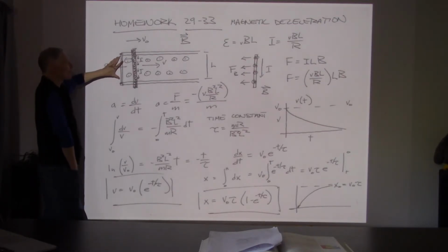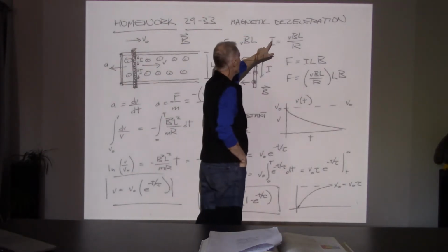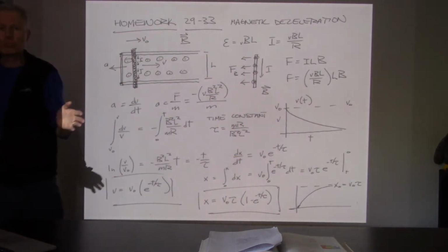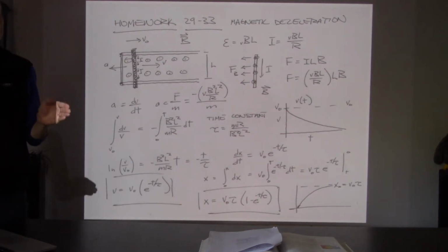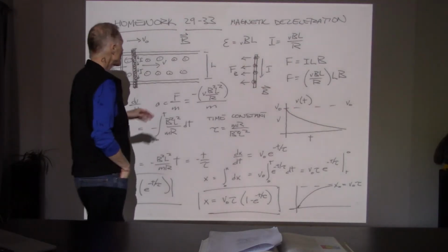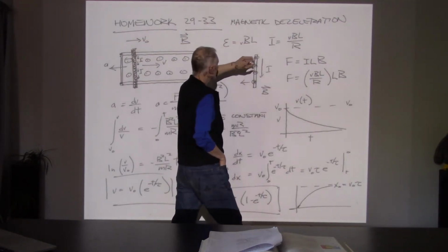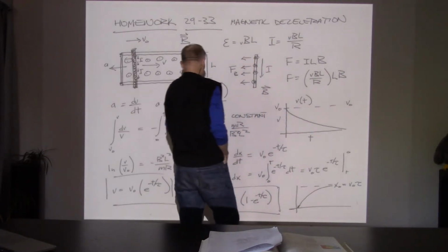Now, what happens once the circuit connects? Well, then we can start driving current through those wires. The EMF is there the whole time. So as long as the bar is moving through that magnetic field region, there will be an EMF generated in that metal bar, from one end to the other. So the EMF is going to be V times B times L, and the current then is going to be the EMF divided by the resistance.